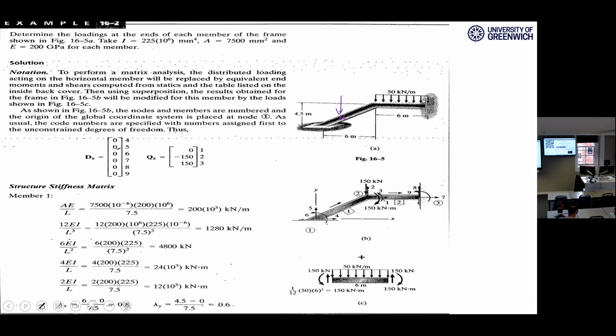But if we don't have a deformation for a node, we will not have a force in our force vector to put that load in. So if you have some load here, you need to say, okay, this is node number 1, 2, 3, 4. This is how it works, for example. But apart from that, if we have a distributed load, we cannot put infinite loads there just to take the distributed load into account. We have probably 2 options.